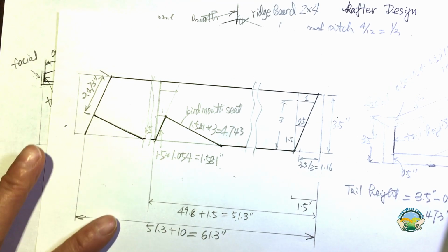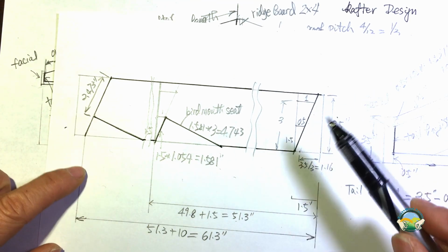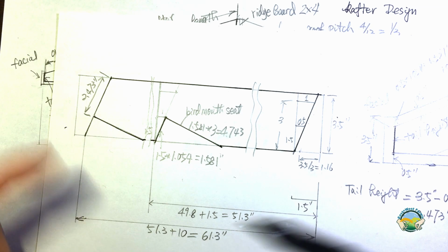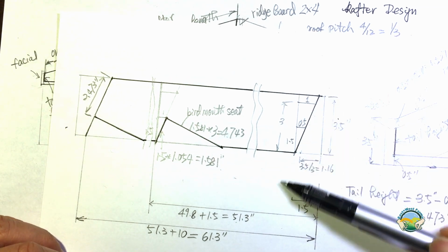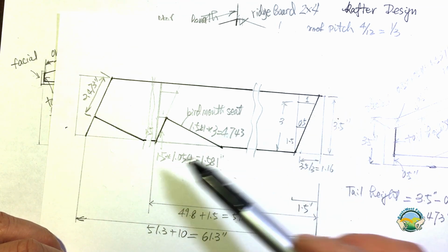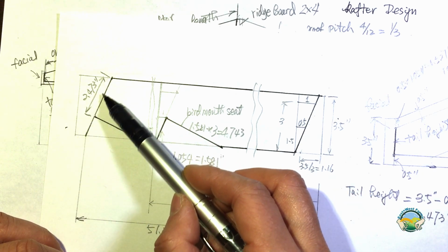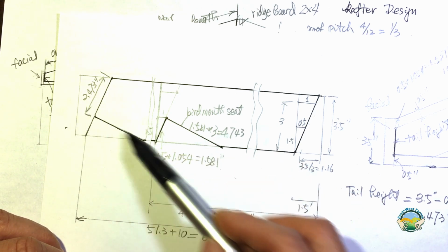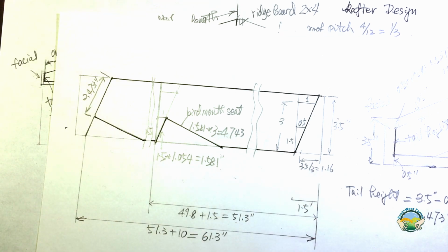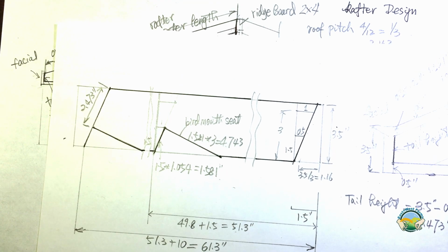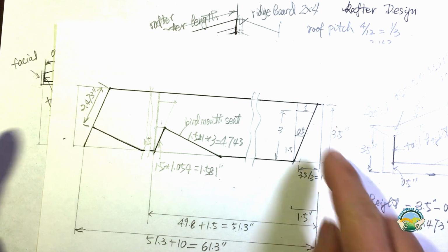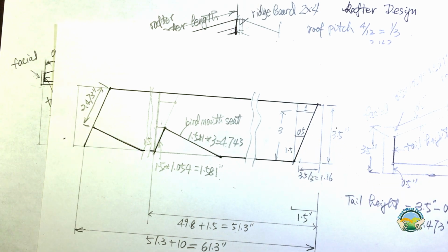That basically is the rafter you have. So you have essentially 5 cuts: the plumb line butting against the ridge board, the bird mouth has 2 cuts, and then the tail has the plumb line and also the horizontal line for the cover. That's the calculation you will use to calculate the dimension of your rafter.